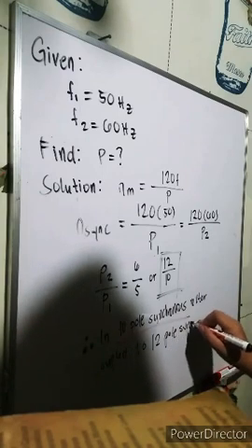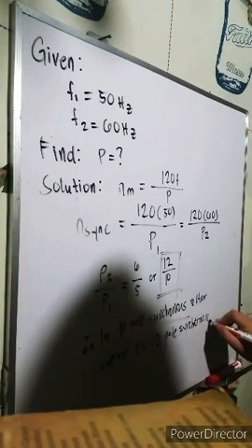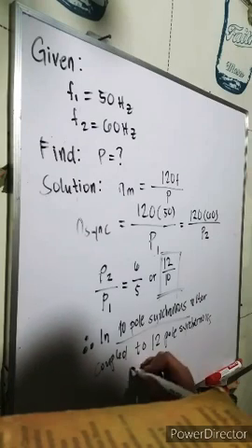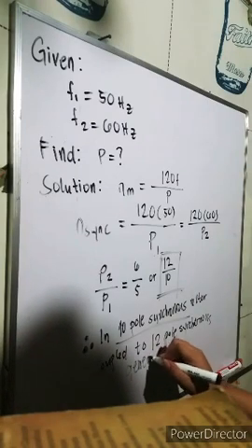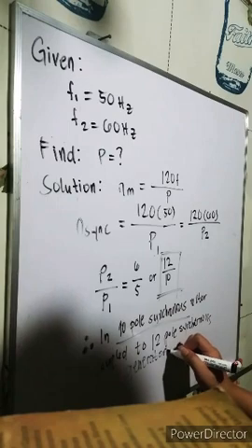Therefore, a 10-pole synchronous motor must be coupled to a 12-pole synchronous generator to accomplish this frequency conversion.